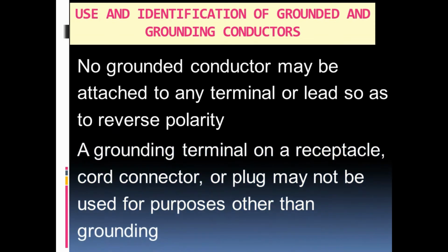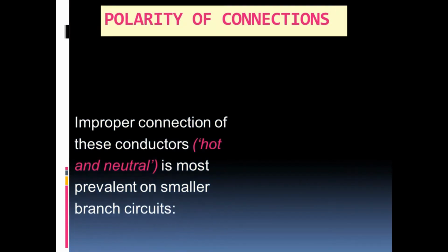No grounded conductor may be attached to any terminal or lead so as to reverse polarity. A grounding terminal on a receptacle, cord connector, or plug may not be used for purposes other than grounding. Polarity of connections.